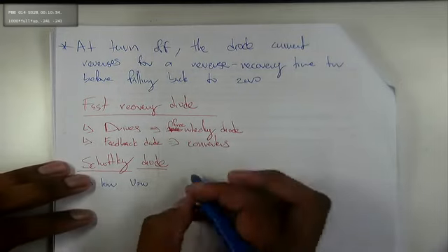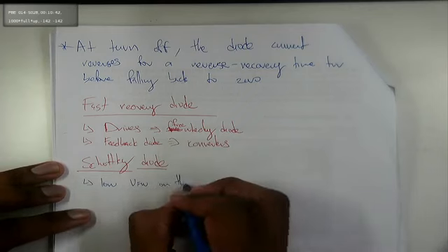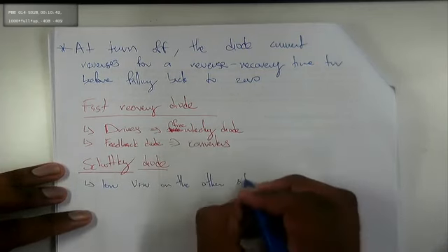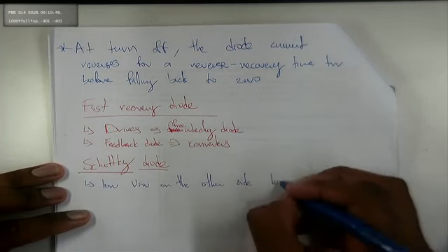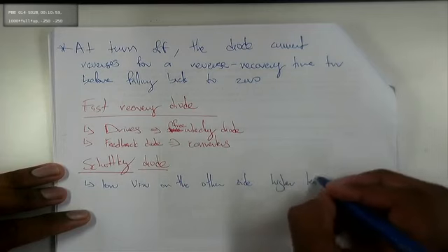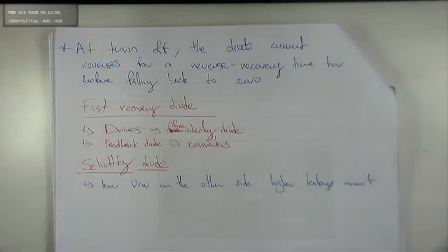So V forward, and on the other side it has higher leakage current, meaning that it can go towards the left hand side of the characteristics before it breaks down further towards the left. It is a higher breakdown on the negative side. It is just like we are offsetting everything towards the left.